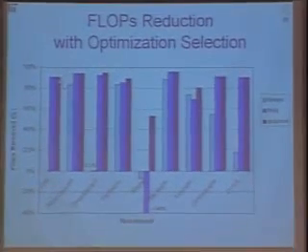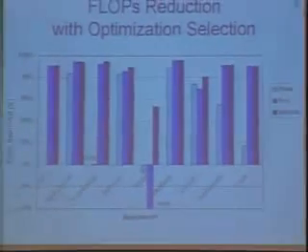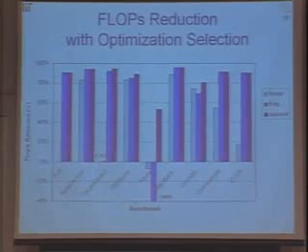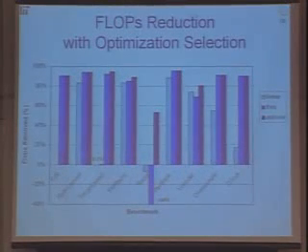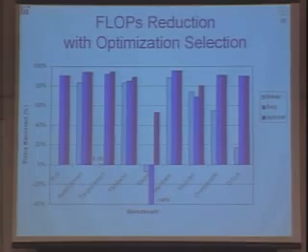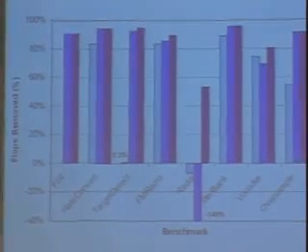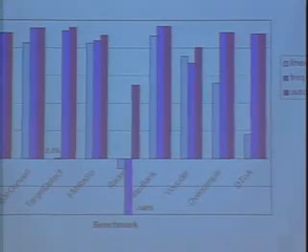So there are 2 other optimizations we did. The second one here is that, in DSP, people go from time domain to frequency domain manually. We said, why don't we automate that? So we look at the program and, instead of doing all these things in the time domain, we automatically go to the frequency domain, do a simplified calculation, and come back to the time domain. It's a very, very tedious process to do manually, because a lot of these matrices have to be transformed, and a lot of weird end conditions have to be met. It's all done automatically and nicely in the compiler, and we get a huge amount of benefit. And then we have an algorithm to select the best transformations to do and get a very good performance boost.